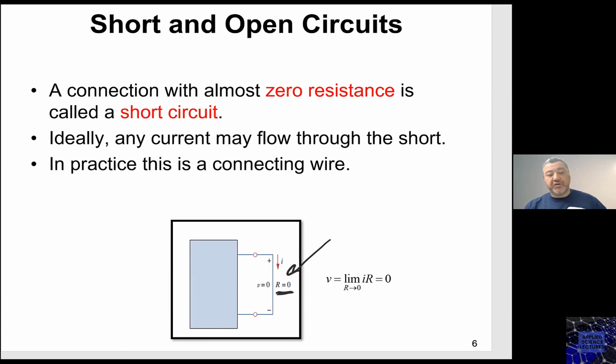If there is no protection circuit for the power source that I am using, I will end up damaging this power source, because I will be withdrawing a maximum current, and this maximum current will result in a withdrawn power that is beyond the capability of this power supply, unless you have a protection circuit in it.